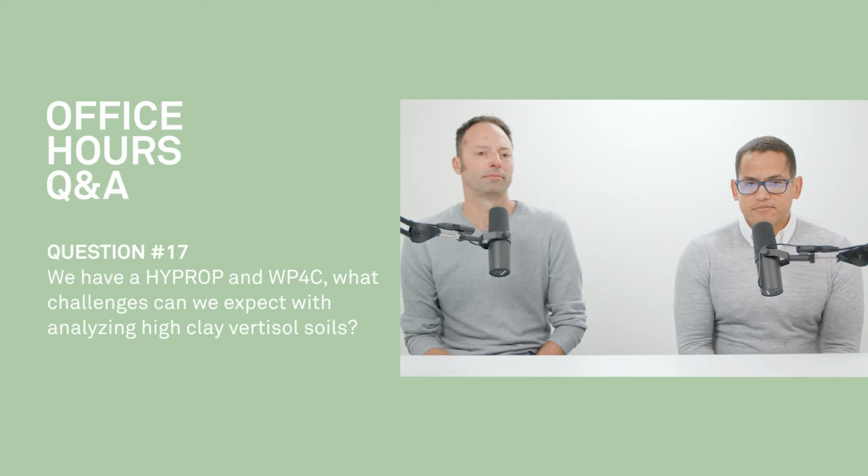Yep. This next person is asking, we have a HYPROP and WP4C. What challenges can we expect with analyzing high clay vertisol soils? It's mostly the shrink swell thing, right? That's the biggest factor, the shrink swell of the soil. None of these methods really handle that all that well, especially as you get it really dry. You get large cracks that form, and it shrinks away from the edge of the rings on the HYPROP. But not just that, you can lose contact with your tensiometers too. Yep, so these vertisols are tricky.